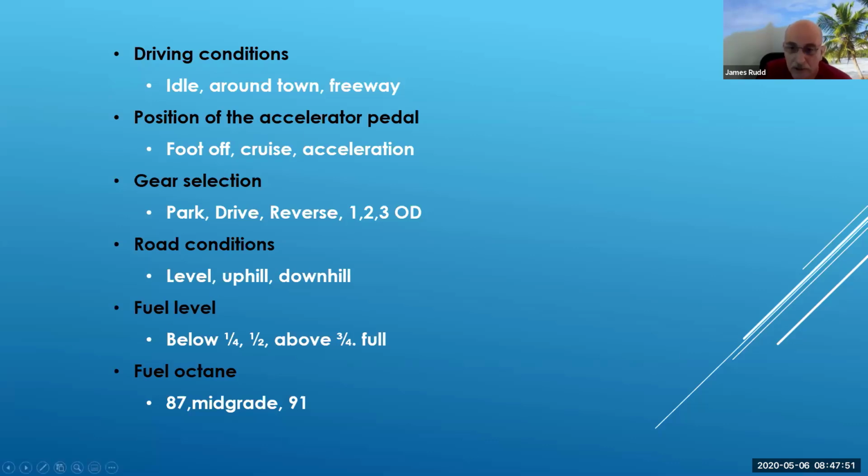Believe me, if you get to something that's ignition breakdown, there's a definite drop feel. If you're talking fuel, it's kind of a progression. With fuel filters or catalytic converters, you're talking about a definite lack of power, not a breakdown. So there is kind of a two type thing that I'm checking for when I'm going uphill. I'm looking to see how it accelerates. Does it accelerate slowly up the hill?